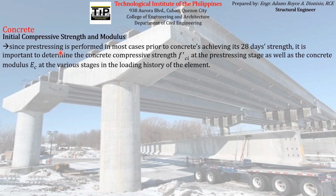We have to take note of that because pre-stressing is performed in most cases prior to the concrete achieving its 28 days strength. It is important to determine the concrete compressive strength f'ci at the pre-stressing stage, as well as the concrete modulus Ec at the various stages in the loading history of the element. Since I've said that the modulus of elasticity is mainly dependent on the compressive strength of the concrete,